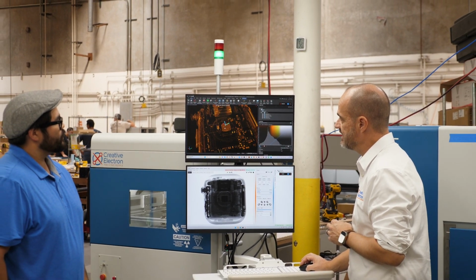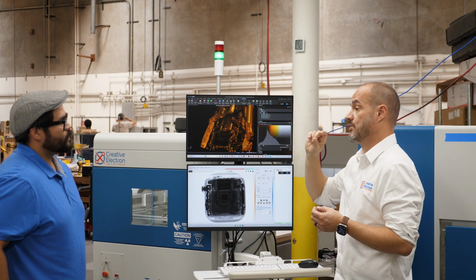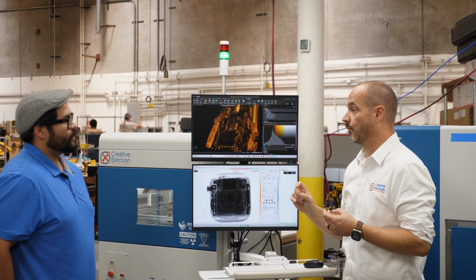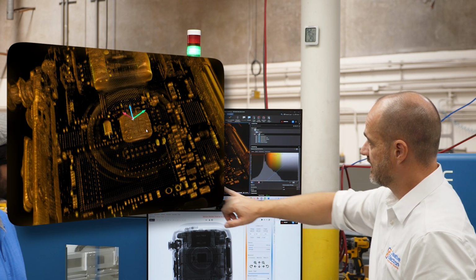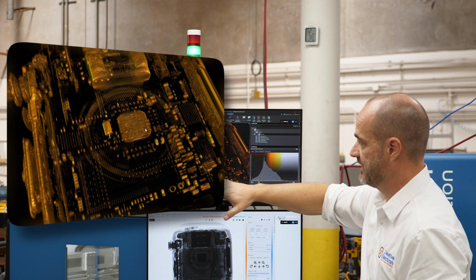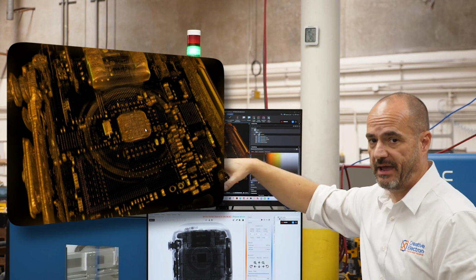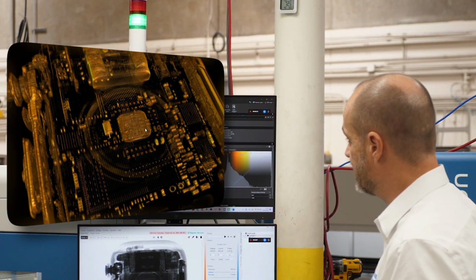As you can see here, we have the tactile engine, the digital crown right here, the big speaker that you can play music with. You can actually use the speaker to get water out of your watch. Anyway, you can rotate and see the solder balls on the BGAs. This device is all chip scale packaging, BGAs, and really high density packaging. You can see the tactile engine here.